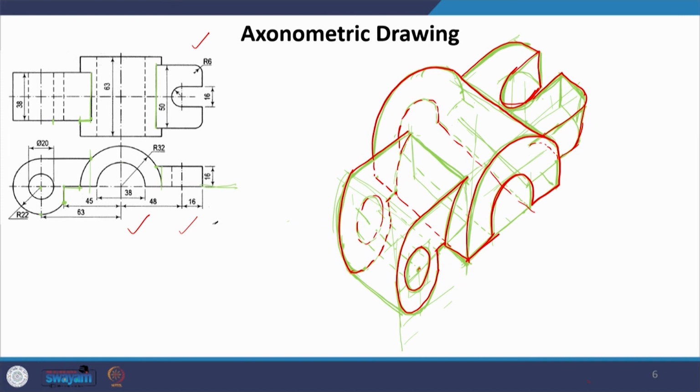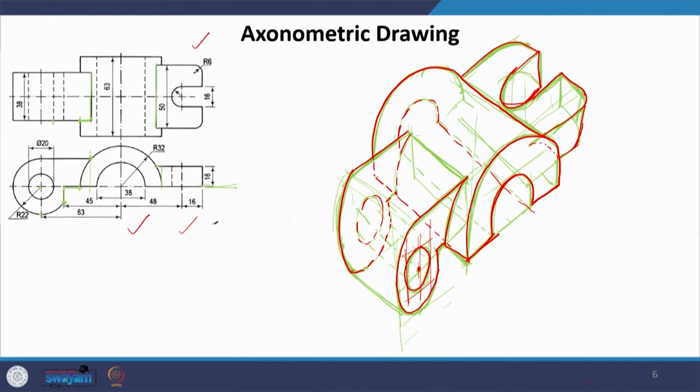So, in case of circles, we arrived at the centers of the circle, also establishing where the diameter and the radius are going to be, so knowing how the circle is going to look. In case of circles, we have to establish where the center is and then define its boundaries, and you can clearly simply draw the circular planes. And for the rest of them, we derived the heights. So, for example, in this case, we derived where this point is going to be, and this was the other point, and we simply understood that this is going to be the curve which is parallel to the original curve, the actual curve of the main object. And that is how you could derive the axonometric view simply from this given orthographic projection.